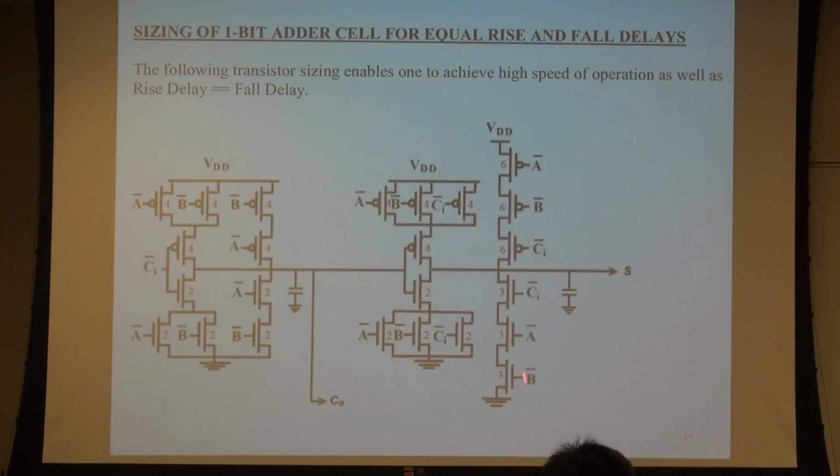am I going to give the same sizing of this as opposed to over here also? There is more probability that these transistors will be passing the signal than these two. So I need to now do what is called the input data pattern analysis. Using the input data pattern probabilistic analysis, I can go back and resize the transistor to further optimize my design in terms of the layout area, in terms of the circuit speed. Am I correct?